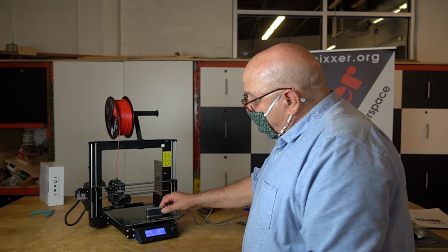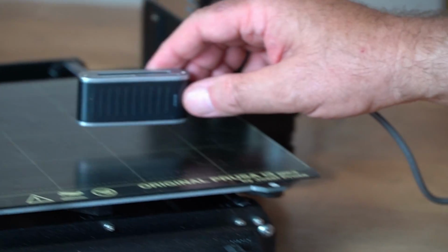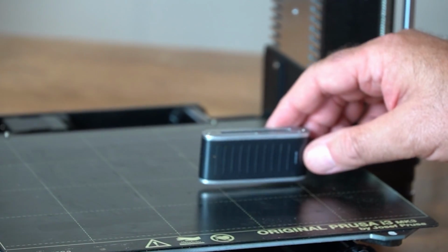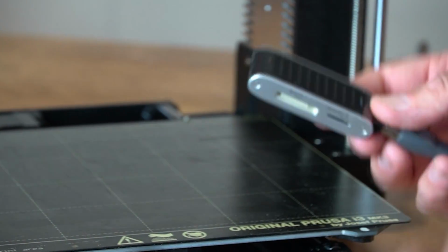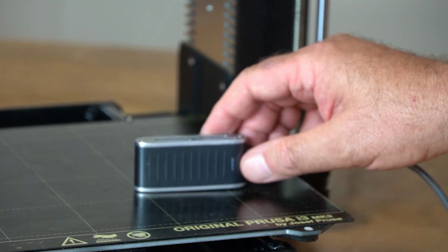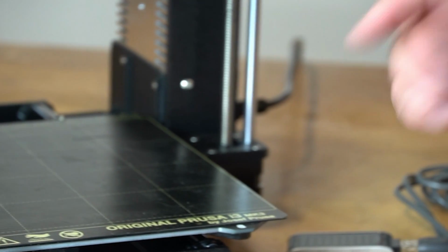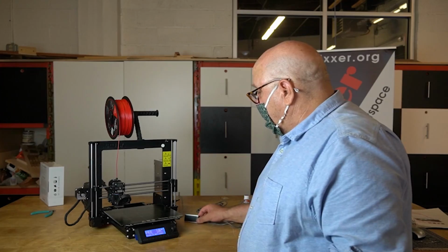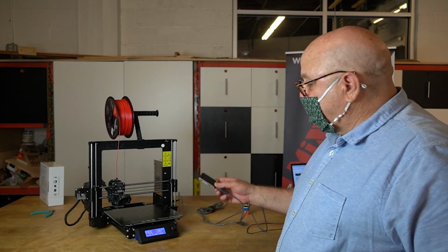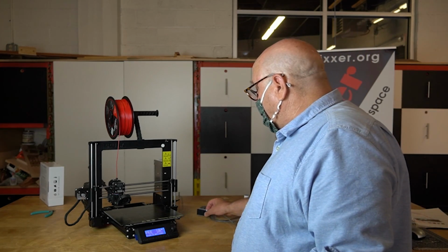If you're printing something that's very narrow with a very small surface that meets the workspace, the bed right here, then you definitely want to use the glue, because what will happen is when it's printing, it could actually push it off the bed. And that comes from experience and understanding when to use glue or not use glue.